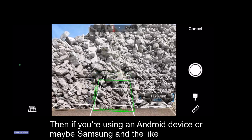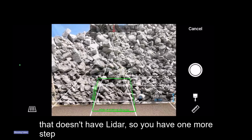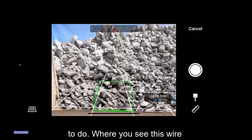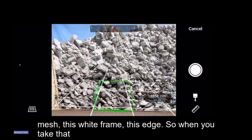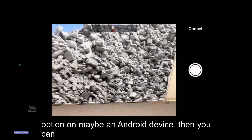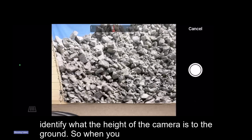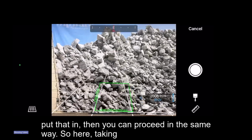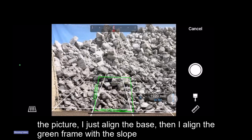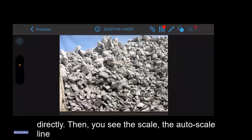Then if you're using an Android device or maybe Samsung and the likes that doesn't have LiDAR, you have one more step to do, where you see this wire mesh, this white frame at this edge. So when you click that option on maybe an Android device, then you can identify what the height of the camera is to the ground. So when you put that in, then you can proceed in the same way. So here, taking the picture, I just align the base, then I align the green frame with the slope, then you take the picture. So in this case, the software is going to import the image directly.